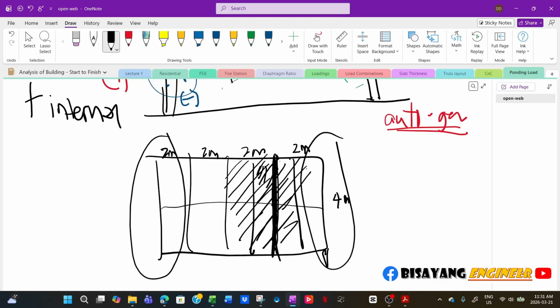If this will be designed as components and cladding or main wind force resisting system. But for designing the lateral force resisting system, you always use the MWFRS, main wind force resisting system. But if you design the truss itself, that is where you consider which one applies.